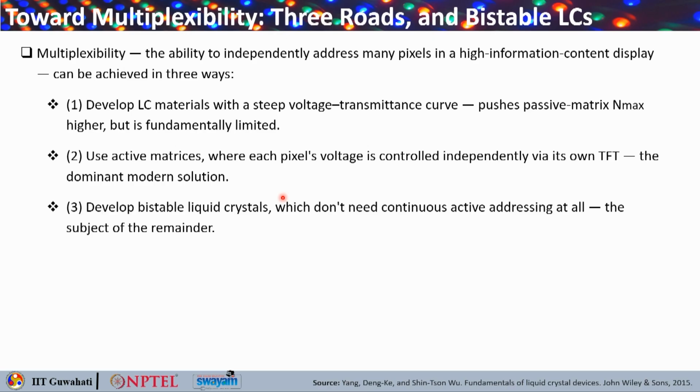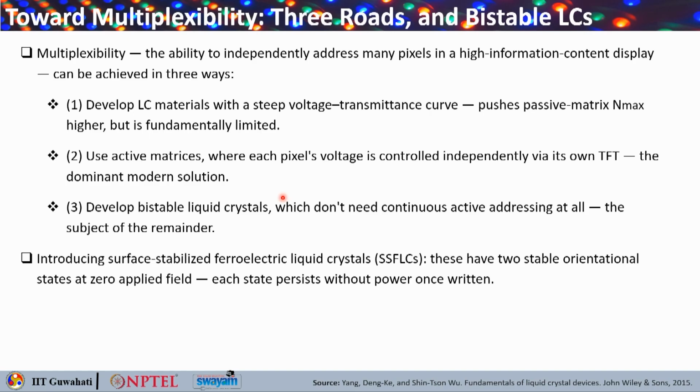And the third one is to develop bistable liquid crystals which do not need continuous active addressing at all. That is what we'll be seeing next. So introducing surface stabilized ferroelectric liquid crystals, or SSFLCs.